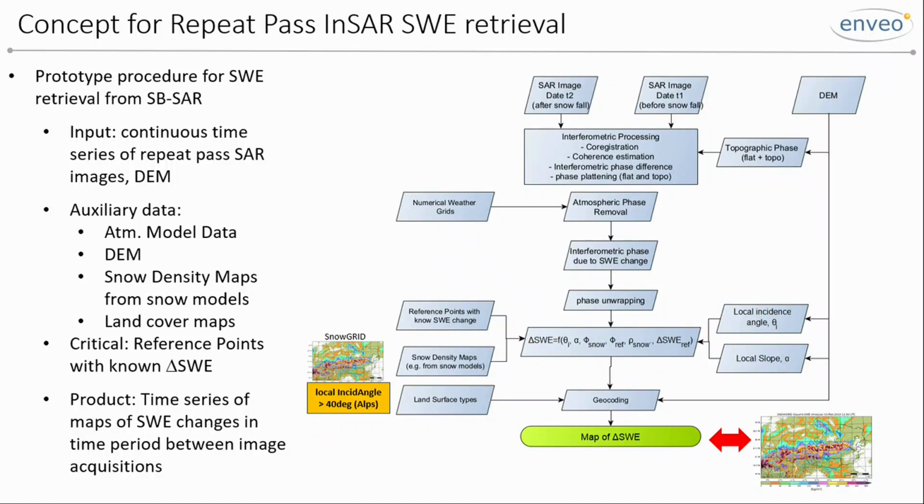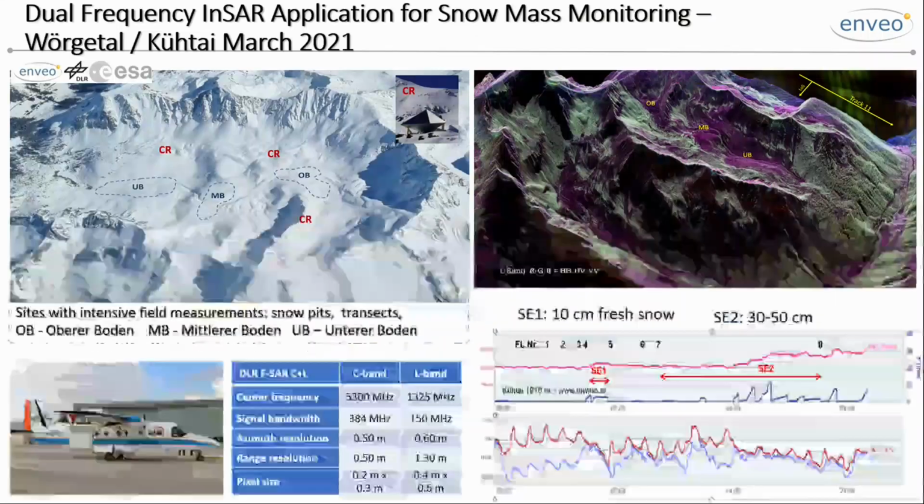From the practical point of view, we are not doing this continuously over the season, not every day. We will not get the data. We will combine it with the snowpack model, which gives you the temporal resolution. In snowpack models, the snow accumulation relies on the precipitation. Precipitation in the Alps is wrong or not accurate enough. Now if I get an update of the amount of snow water equivalent every week, I can update the snowpack model and bring it back to reality, which is a big step forward. So that would be the application when you go towards an operational one.